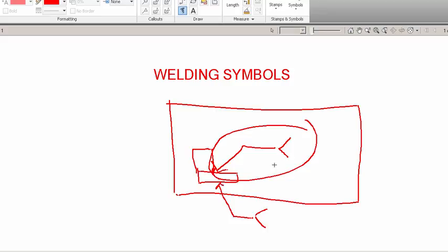Don't assume that because one weld has a certain specification on it that you're going to do it every single time unless you see something like TYP, which stands for typical, and that does imply that it's being used more than that one instance. But for the most part, you always have to be cautious and not make assumptions about that.